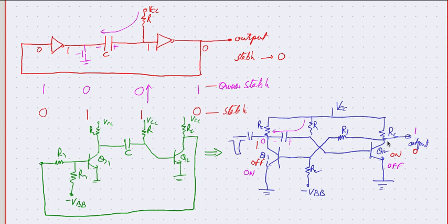And once it is cut off, this voltage goes high. If this voltage goes high, then current starts flowing and this becomes on. Then this goes low, and we don't require any more pulse here. This low is sufficient to keep this off, keep this on. That continues, but on becoming zero here, current starts flowing, and that is an automated process, and that ensures that this is going to remain off only for a fixed period controlled by R and C values.